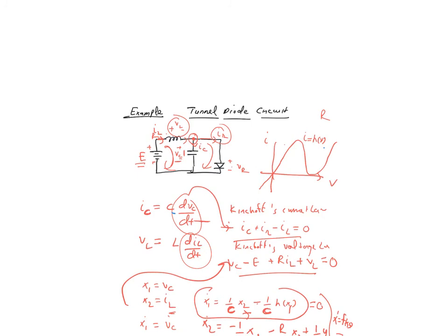So you buy a diode, right, from the market, and they give you this characteristic. This is how it behaves. For this diode, they give you a characteristic equation saying this is how this diode behaves. It increases, and after this point, suddenly the voltage will drop, and so this is the characteristic of the diode that you have put in your circuit. Okay, so this h of v, that function will be given to you. Right now we are saying this is a general function, but this curve will be given to you.